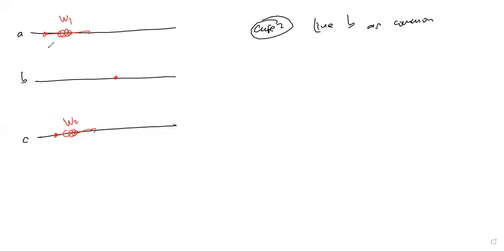So how do we arrange the potential coil? First you need to draw the potential coil of the two wattmeters like this. The potential coil for wattmeter 1 is connected in A itself, and the second terminal is at the common point. For wattmeter 2, it will be connected in C, and then it is connected to the common point like this.